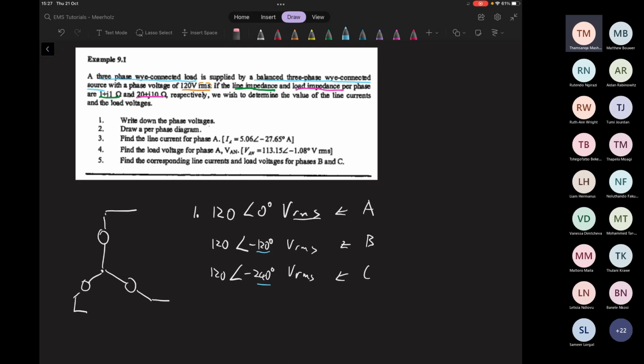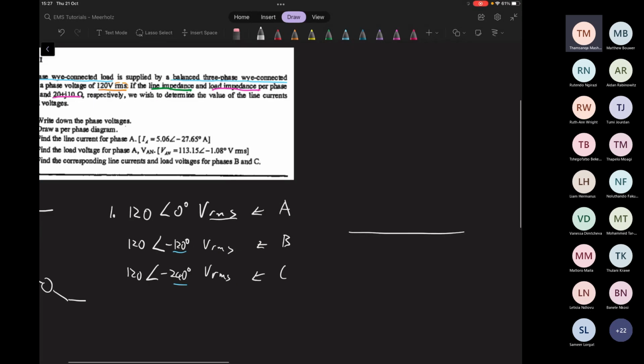Okay, so that's phase A, phase B, phase C. You see, we're going around the circle. If we had a phasor diagram, we can choose any one to be a reference because phases are things that rotate over time. We did this whole thing when we used Euler's identity to represent cosine waves, and then you can add them together and treat them like vectors.